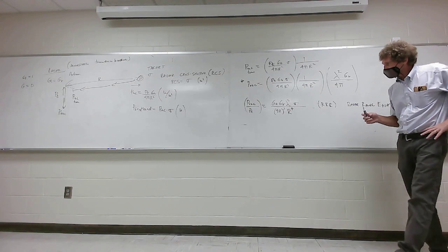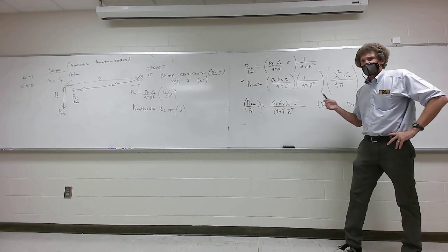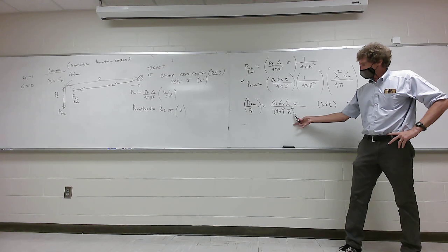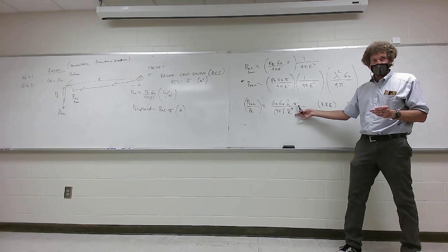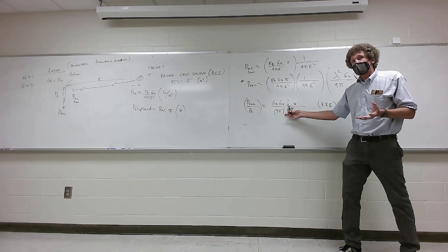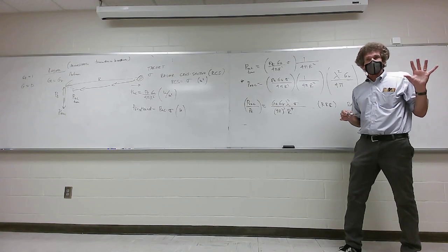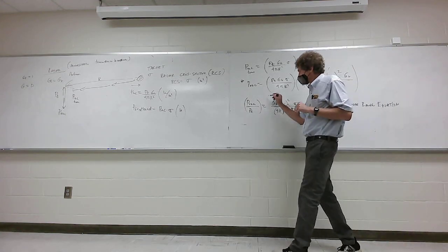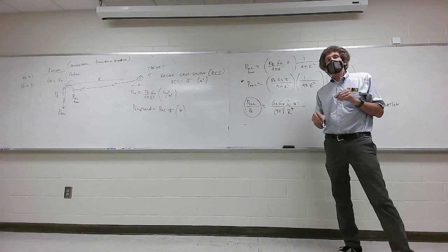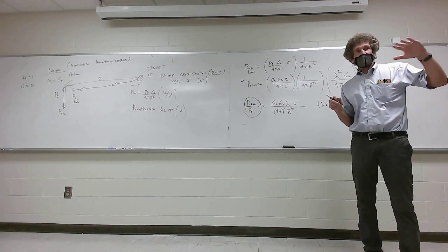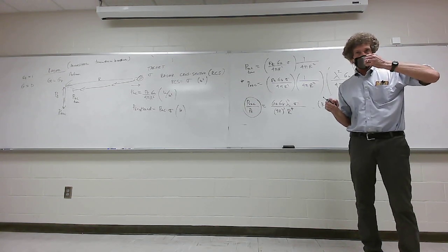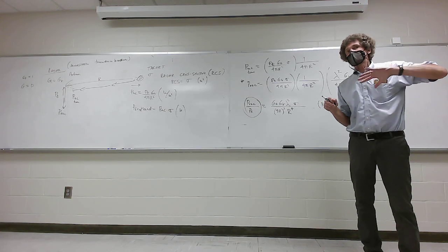And here's why. You see this figure right here? We have an assumption of a distance, a maximum distance. That gives us the range. We know the smallest target, that would be a value of sigma that you expect to be able to resolve. Then you'll know the frequency, so you have lambda. With me on that, class? These gains are things you can adjust. But what usually amounts to is this ratio is something that's critical, and here's why. There will be noise power that you will be able to estimate in your amplifier system from the entire process. And you want that signal to noise ratio.